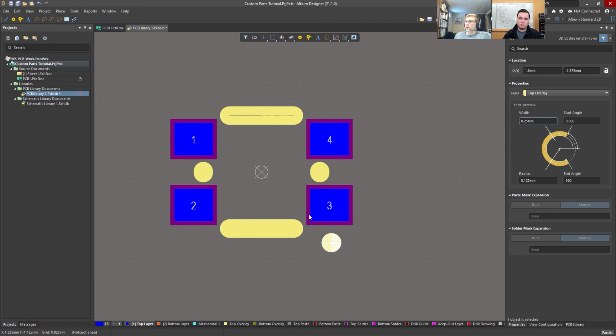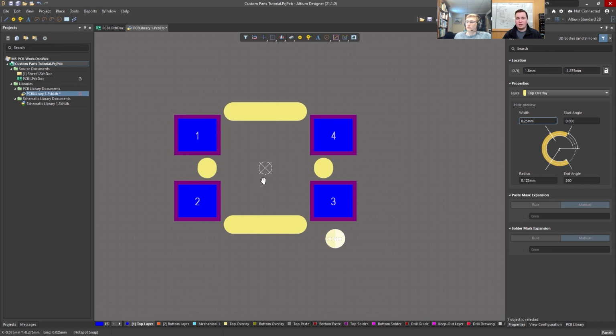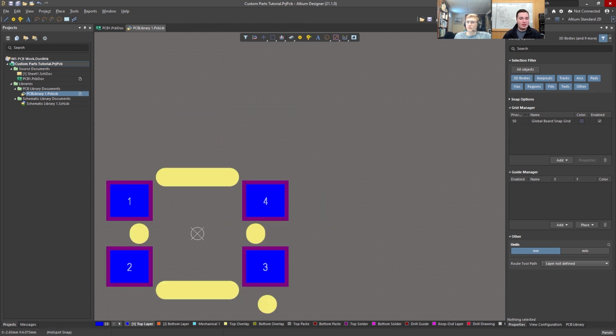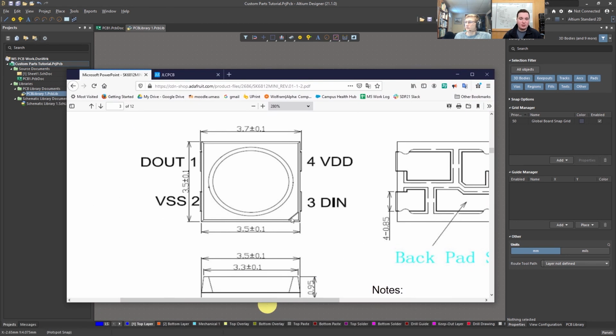Cool. So usually this dot goes next to pin 1, right? So this could be a little confusing. What do you think? Yeah, so rule of thumb standard is dot goes next to pin 1. However, we looked at the data sheet, and we have some in front of us. So we know that even though that's labeled pin 1, the dot goes in the other corner. This is very unusual to see, but it's something you might encounter. Right. Yeah, that's a little bit confusing, so you got to be careful.